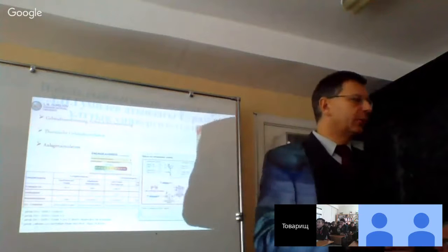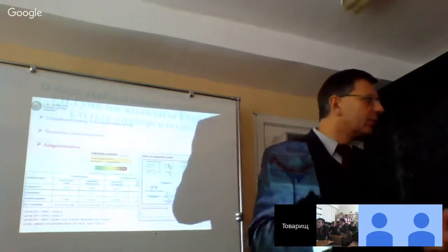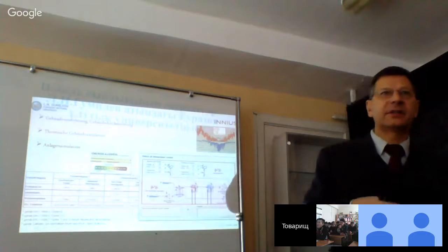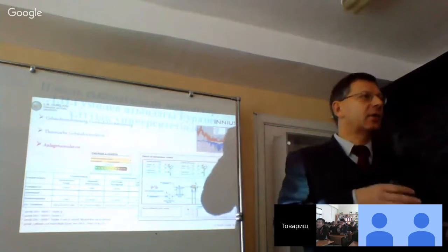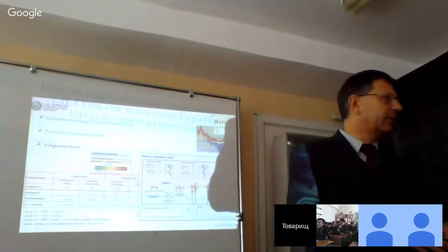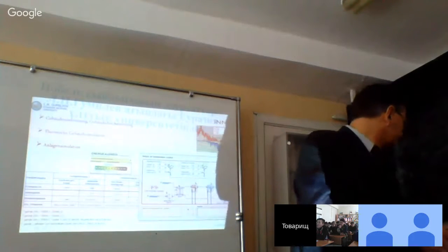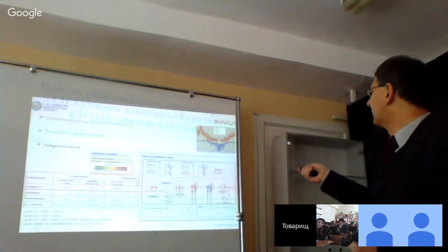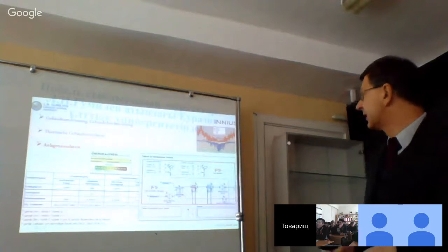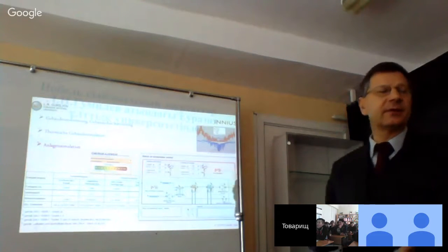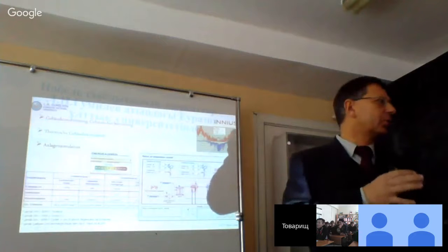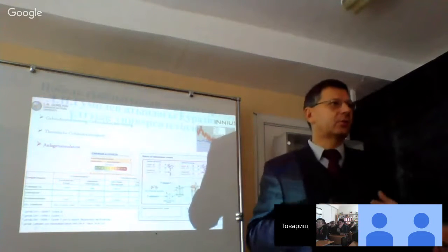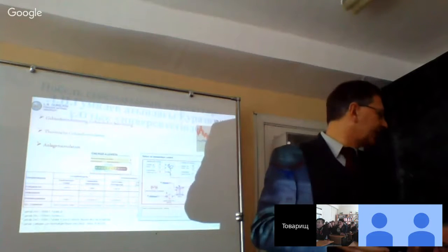And the new possibility with plant simulation is that you can estimate the behavior of the technical equipment in front of construction and of running. That's very important. That means you take, like you see in this diagram, the heating load and the cooling load, put it through your technical system, give the control parameters, and then you can show how the system works. And you can define the control algorithm for the building.